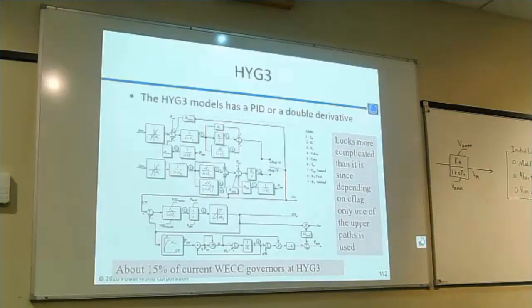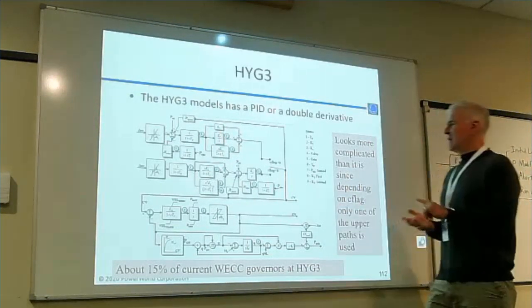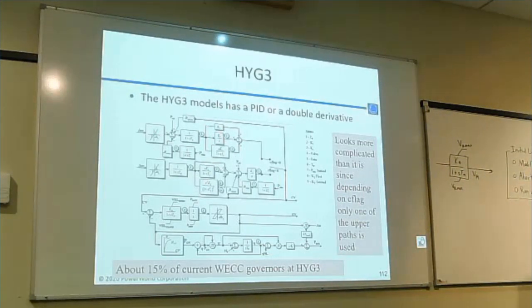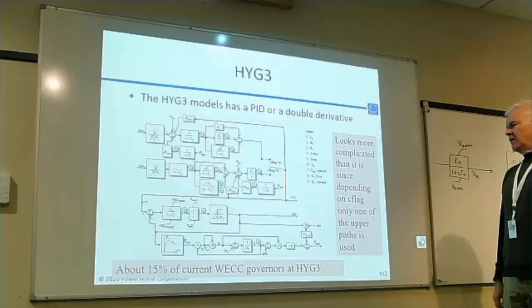And that's something that's added to the governor to tune its response. I mean, a PID controller is not a hard controller to add. And you're only tuning the proportional gain, the integral gain, the derivative gain, and its time constant. And that's what the tuning method that we just went through will tell you. It's just saying what sort of response do you want out of this.